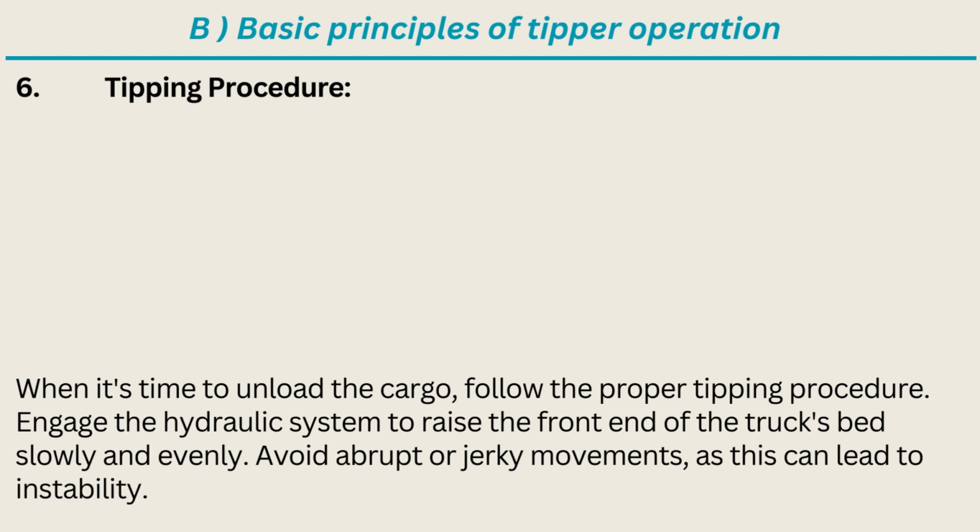6. Tipping procedure. When it's time to unload the cargo, follow the proper tipping procedure. Engage the hydraulic system to raise the front end of the truck's bed slowly and evenly. Avoid abrupt or jerky movements, as this can lead to instability.